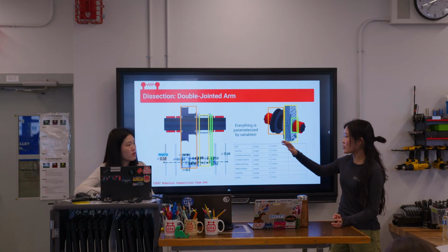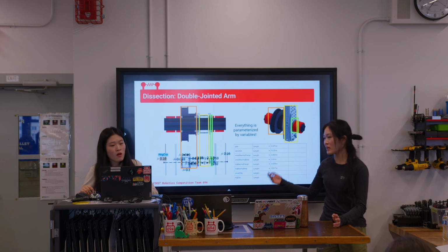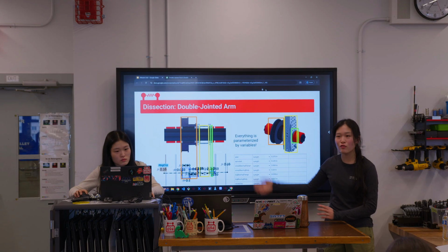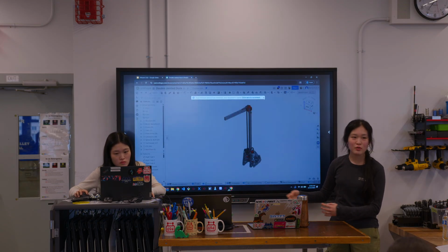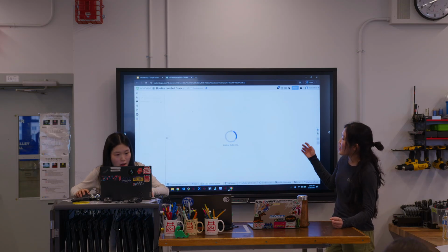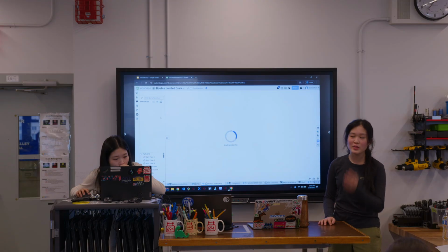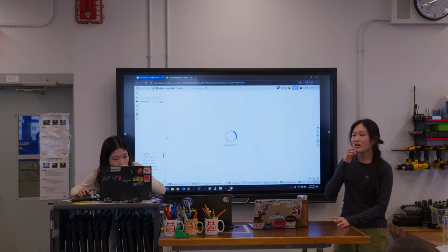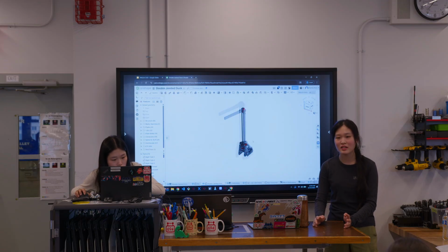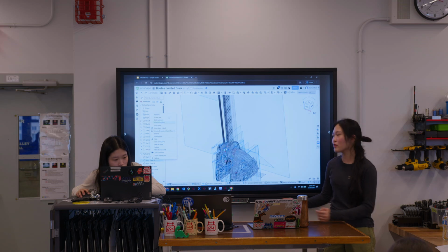I think it depends on which sketch you start off with. So let's say you're making a double jointed arm on your robot. You might have the side view of it in the robot master sketch because it's such an important part. You need the pivot points to be represented in the robot master sketch. And then in the mechanism master sketch, you'll maybe add the axle sketch. But there's usually not a clearly defined line of up to here must be a robot master sketch and up to here must be a mechanism master sketch, because if you create a sudden boundary, you get more limited.